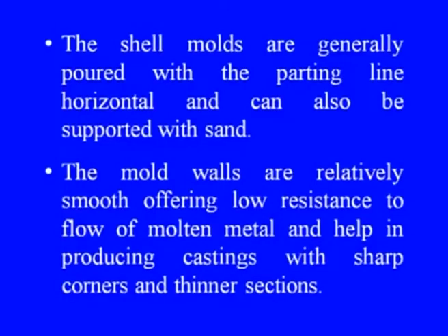It provides excellent surface finish. The cells have to be properly vented, as a high volume of gas is evolved due to the resins and binders used. The cell molds are generally poured with the parting line horizontal and can also be supported with sand.